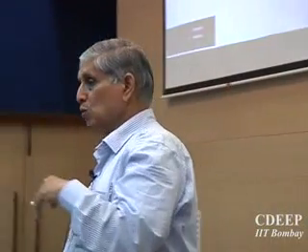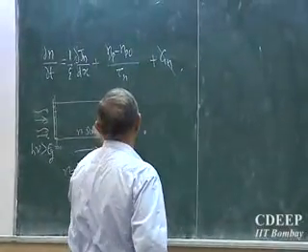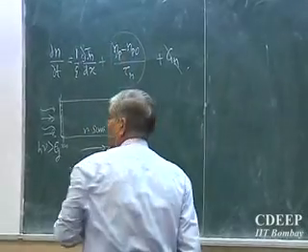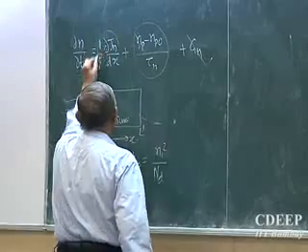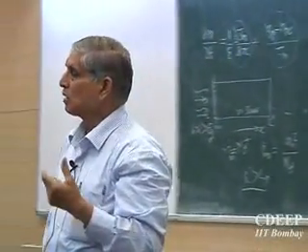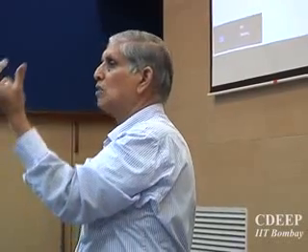As the carriers move, they also recombine. Okay, so there are two mechanisms which are shown here. Right now we neglect this because nothing is generated here. So which term are we talking about? Recombination. This term is because of gradient diffusion. So the two mechanisms are trying to bring the system to equilibrium. That is what it is. You have created a non-equilibrium situation, and now the system wants to come back to equilibrium.